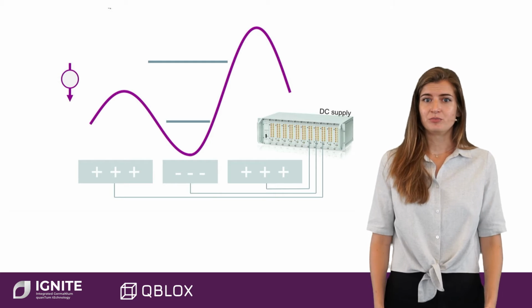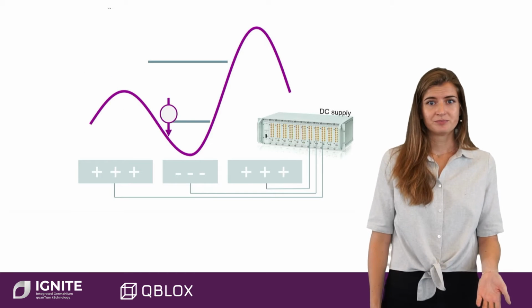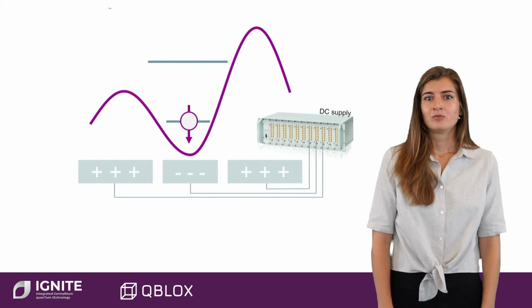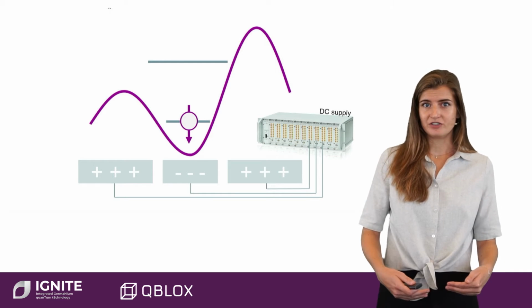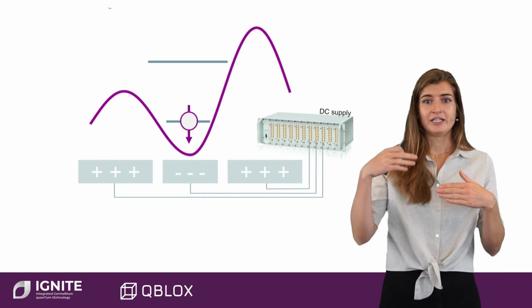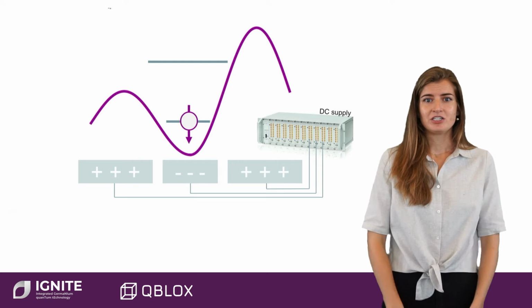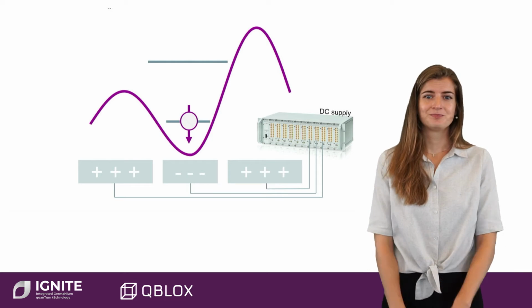By varying the tunnel barrier, a hole can be loaded. When the system is tuned such that the spin down level is below the energy of the lead, while the spin up level is above it, the system can be initialized in the spin down state.